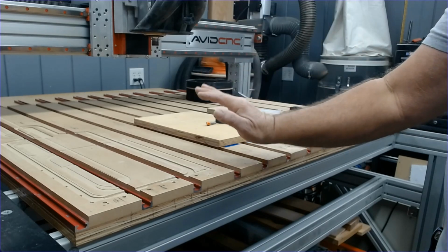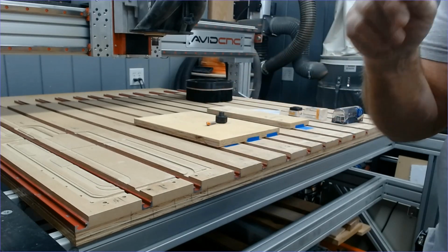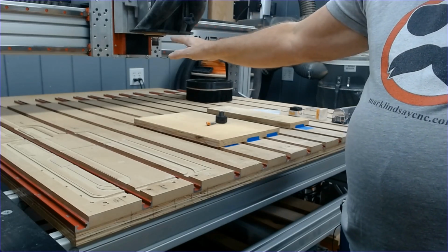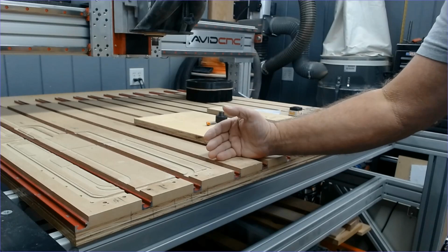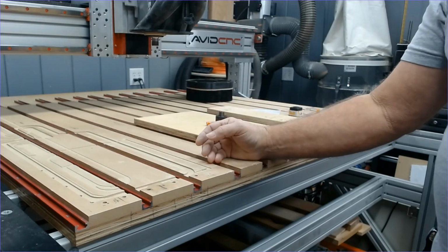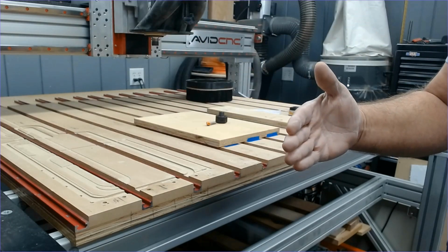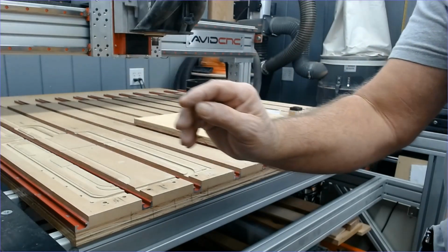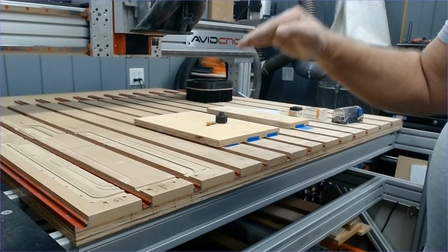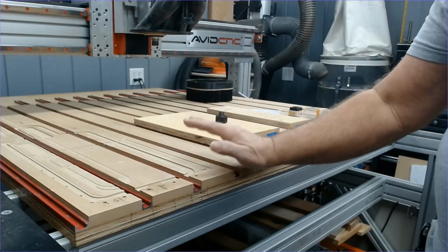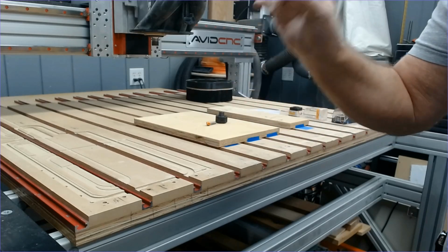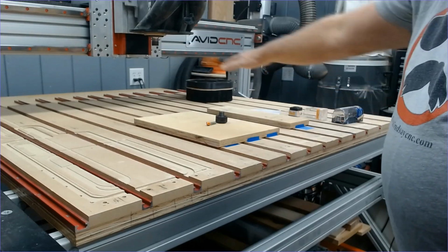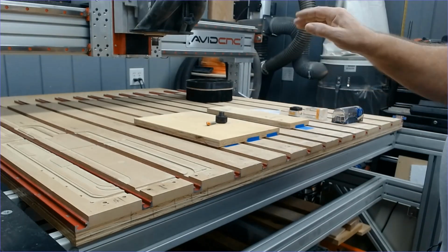It's also important that your controller software knows where this spindle is at all times. That's why we home the machine. When you home the machine, the gantry moves forward to its limit, your x-axis moves to its limit, your z-axis raises to its limit, so that the controller software knows where that spindle is in reference to the table of